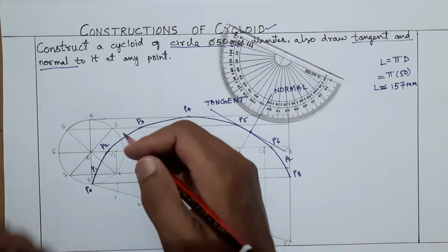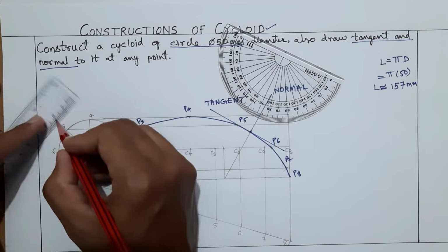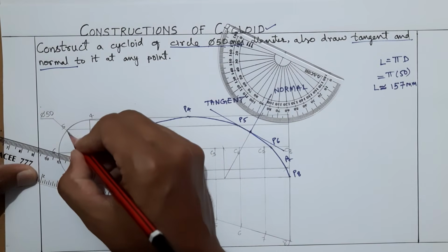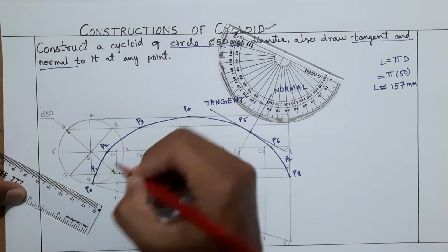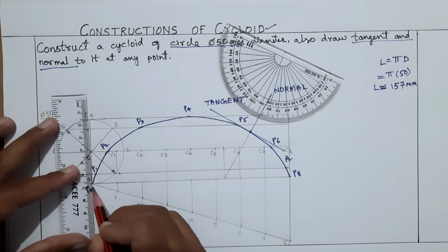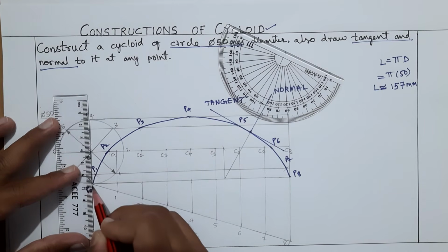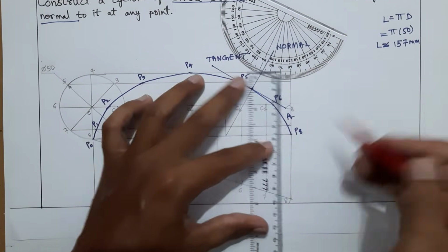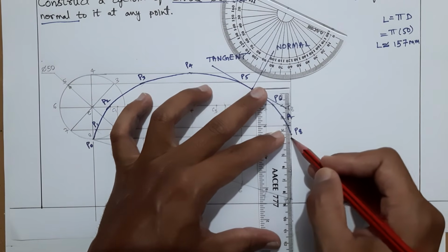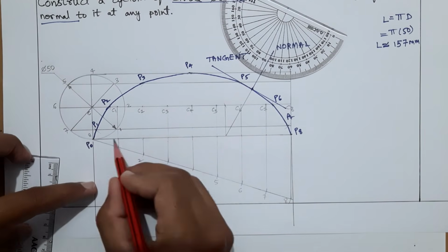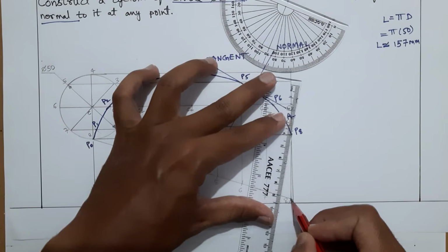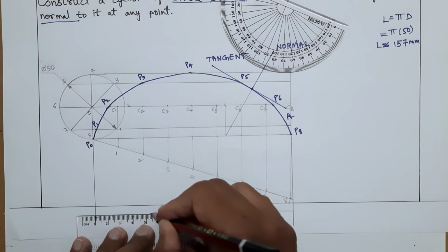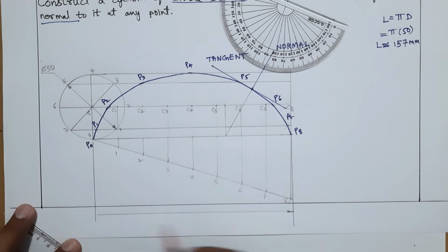Okay, so dimensions are left out. Do the dimensions for this circle. I'll take directly with this leader line dimension. So here is 550, and I'll make this as 2 arrowheads. This construction line itself is the dimension line. Here leave some gap from this point to here, approximately 2 mm, 3 mm. Take a thin continuous line downside like this, and here also you take like this. These two lines are perpendicular to this baseline. Okay, so this point is slightly pointed this way. Here you can do the dimensioning part. Arrowheads,